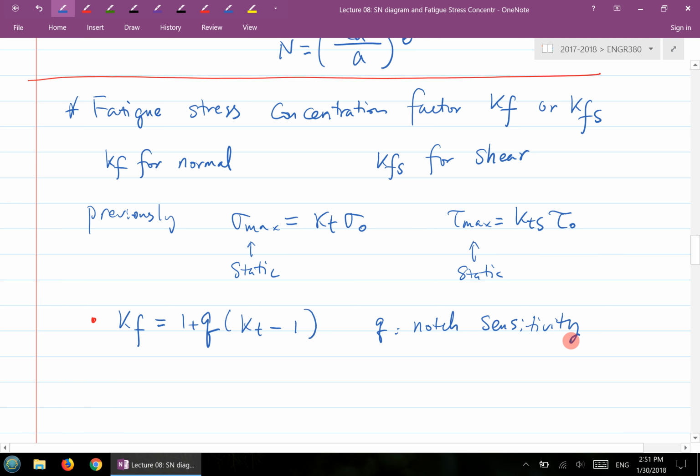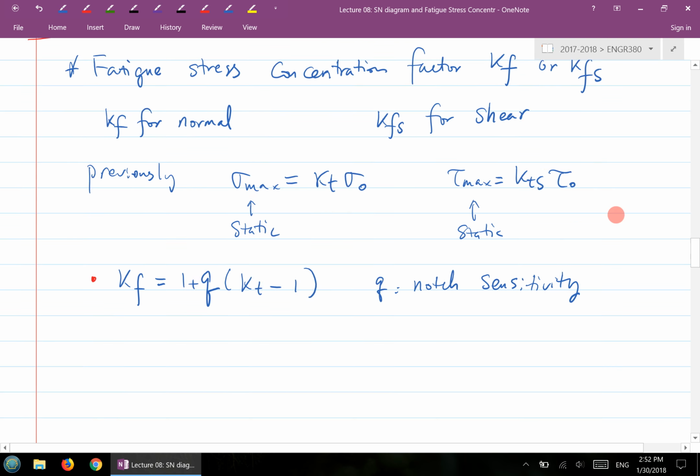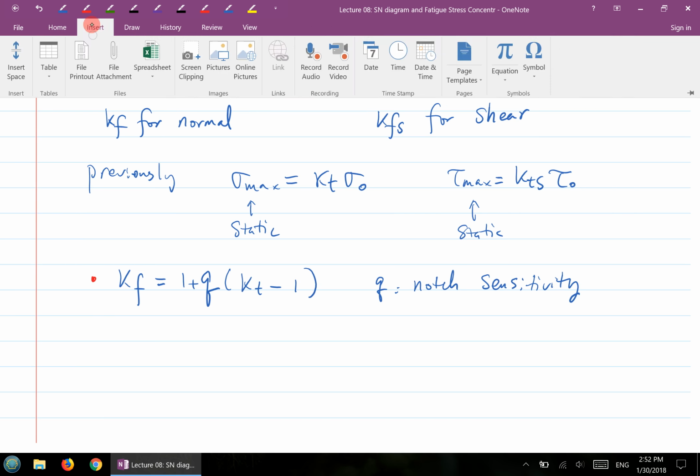And sometimes it's a testing point, right? Yeah, to confuse you. However, when it comes to the fatigue loading, it doesn't matter whether it's a brittle material or a ductile material. Both of them will feel this stress concentration. Both of them will be equally sensitive to this stress concentration at the notch area. So the point here is the differentiation.